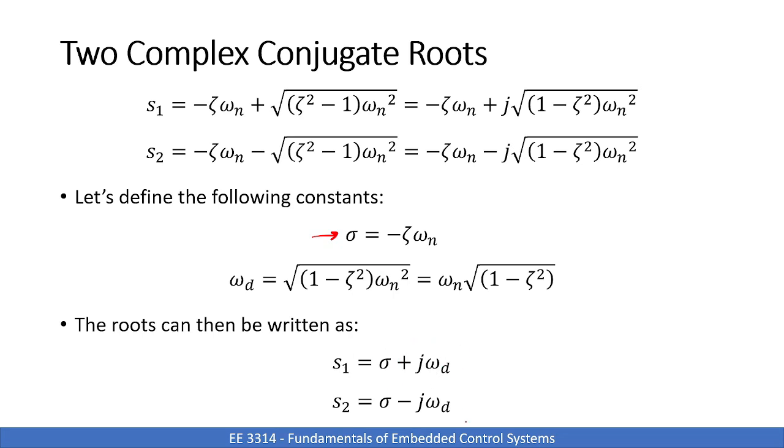If we're going to plot these in the complex plane, this makes it a lot easier, right? If we have our complex plane, or our S-plane, you can see that now we have sigma and j omega. That's something we can plot in the Laplace plane pretty easily. So this would be sigma plus j omega. And what we'll find is that the location of these roots in the S-plane is going to determine a lot about what our system response looks like.